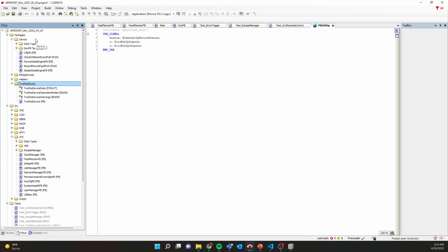A control valve has an A port and a B port, and when the A port's pressurized, that's what I would call whatever the cylinder moves to. I would call that position A. Whenever the B port is pressurized, that's what we would call position B. And the associated sensors to detect those positions would be sensor A and sensor B. So yeah, some reuse code there.